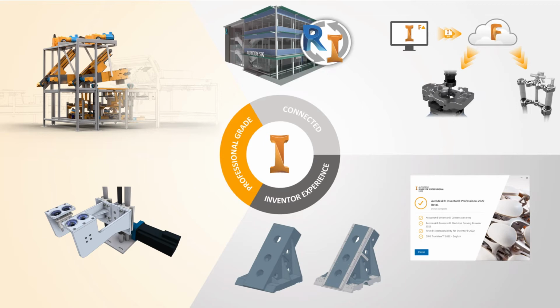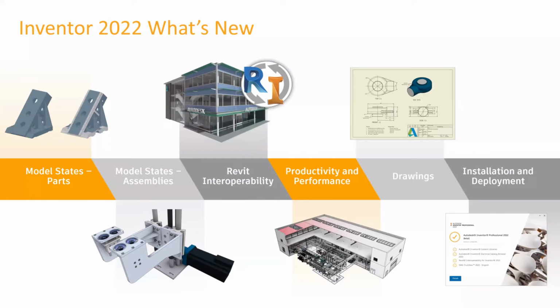So we've basically divided this up into sort of 3 sections, I guess. First up, like I said, we're going to be talking a bit about model states and the way that they behave, and how we can separate out manufacturing operations, dimensional variations, and simplified representations of models all in the one part file. A little bit like some of you may have done before with iParts, we've now got this functionality built into what we call this model states functionality.